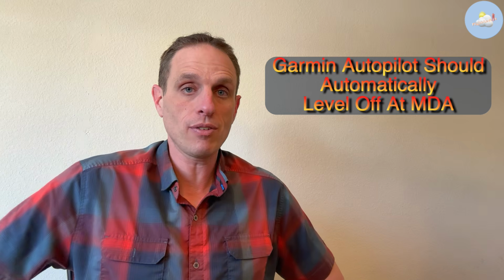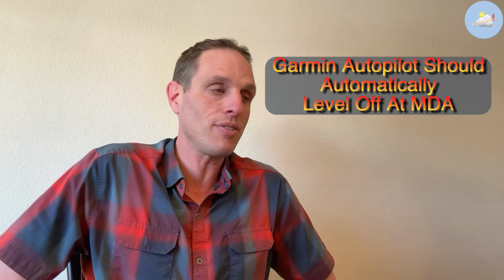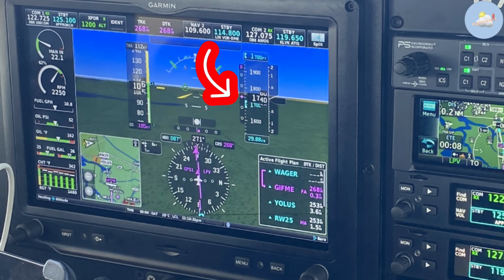Now, here are some arguments that I've been reading a lot about. One of them is that Garmin should have designed these advisory things and their autopilots to automatically level off at the minimum descent altitude. Well, my response to that is that it completely defeats the point of continuous descent on final approach. And that would not be consistent with how autopilots follow any glide slope. Garmin is consistent by having the autopilot behave this way, whether you're flying an ILS, an LPV, or one of these advisory ones. It is consistent.